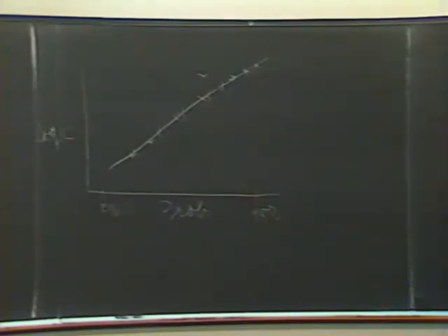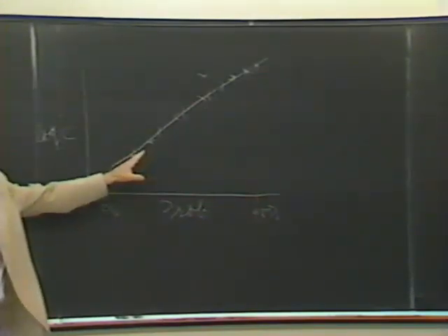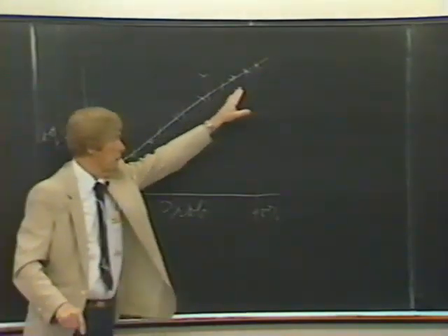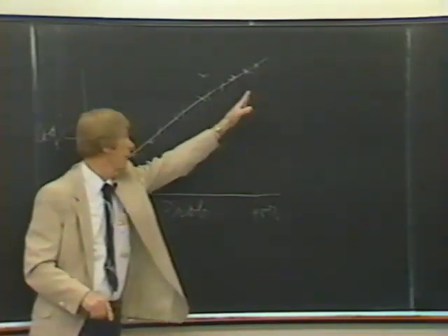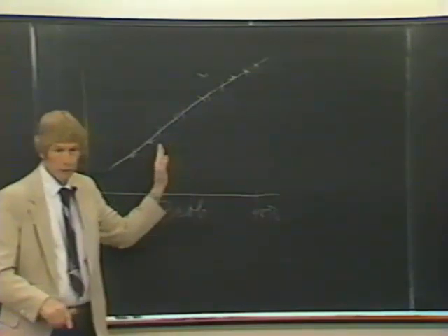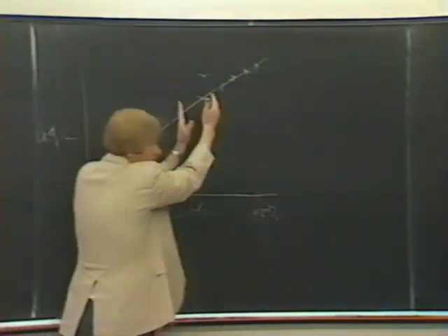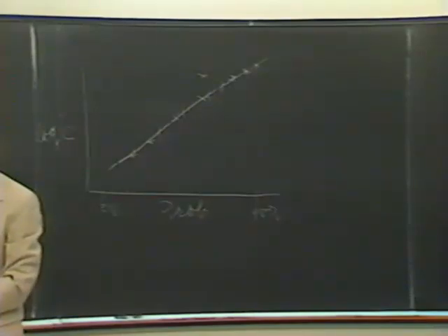A way that the Waterways Experiment Station does it is to use a system quite similar to this. That is to rank the storm inputs from the least to the most, and then take representative storms at the high end, say 3 or 4 different storms, and model them and say that represents the portion of time that you allocate to it, and sum them all up. That's a simplified description of it, but that's essentially what they do.